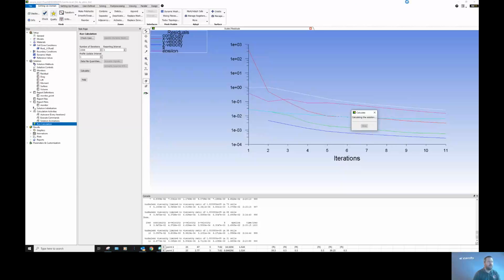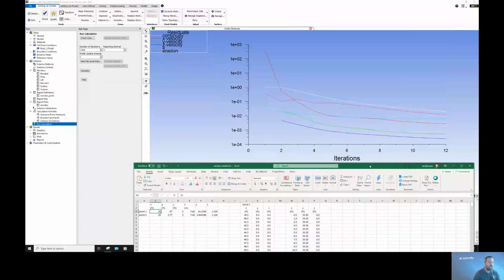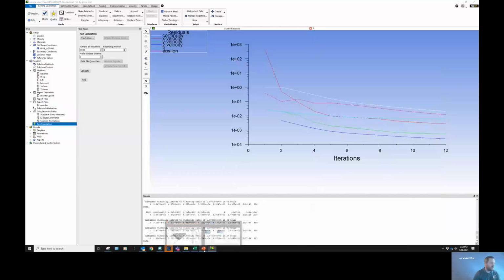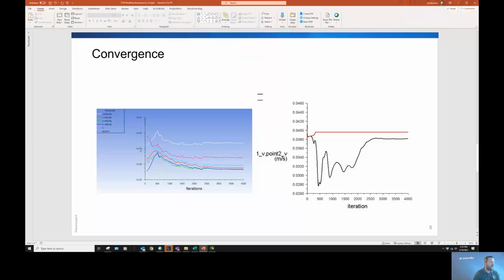And so rather than going through the process, we have pulled some of the output to take a quick look at. So we've set it up, and our convergence curve on an example would show continuity in this case, rising and falling depending on the initialization, everything's big. Most of the values here are less than 0.001. The continuity is a little bit unstable in this case, and it's converged slightly above where we normally like it, but it's not changing.